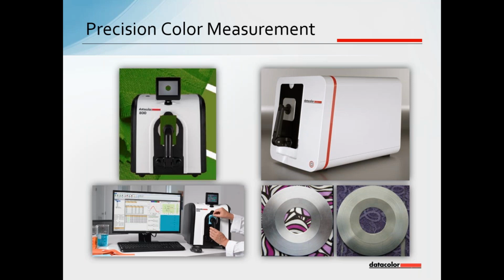At the heart of it is the instrument. Because we're sharing data, we want to ensure that we are working with what are called close tolerance spectrophotometers. That means that the instruments measure almost identically to each other. So if I measure a standard on one instrument, then I measure that same sample on another instrument, the results will be very, very close. In effect, eliminating the need to send the physical sample.